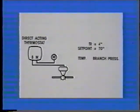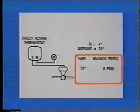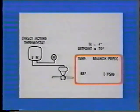This room thermostat is a direct acting device and has a throttling range of 4 degrees. We have a given set point of 70 degrees. At an ambient temperature of 70 degrees in the space, the branch line pressure will be 9 psig, or the midpoint between 3 and 15 psig. Here we have a change in temperature with the temperature falling to 68 degrees. At 68 degrees, or 2 degrees less than the set point, our branch line output pressure would change to 3 psig.